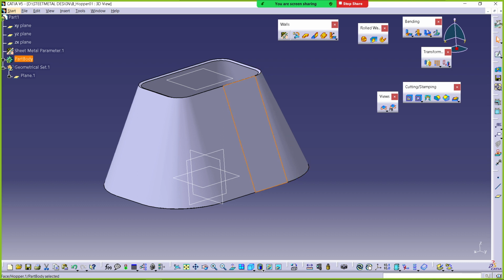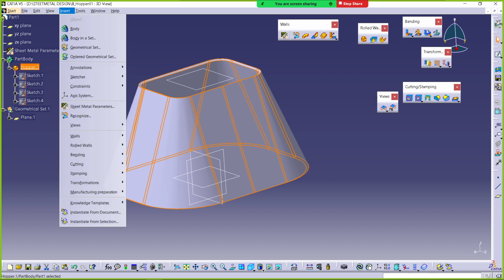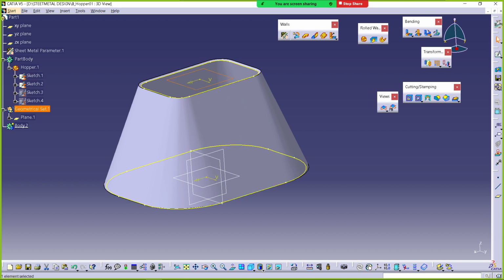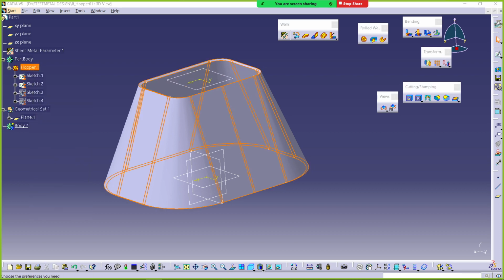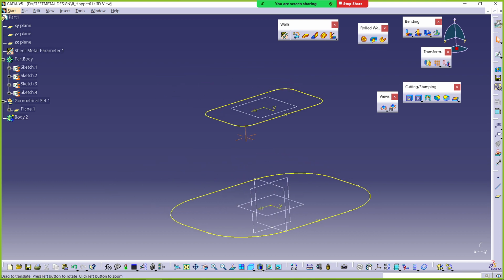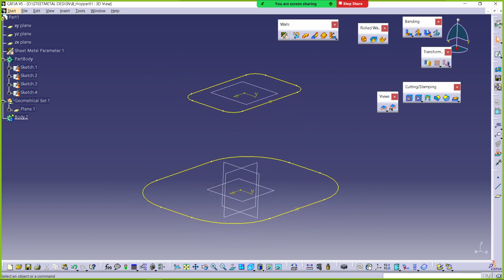And another is the surfacic hopper. For that, let me create another body, just hiding this and deleting this one. So this normal hopper, there is no doubt, I believe. How do we create the hopper? By using the two profiles. And remember, whenever you create the hopper, you need profiles which are parallel to each other. Are there any doubts on this hopper, guys?